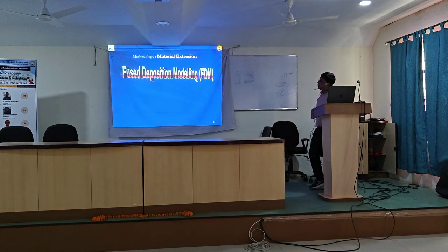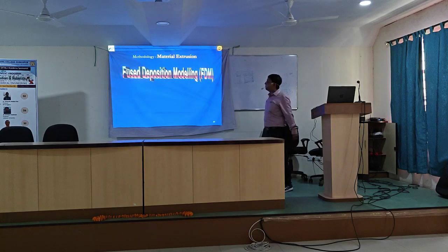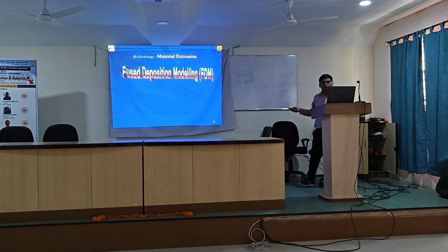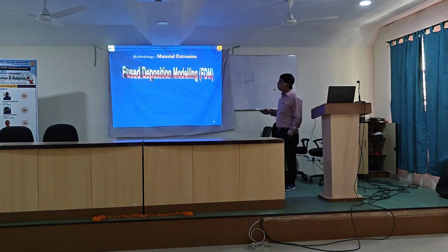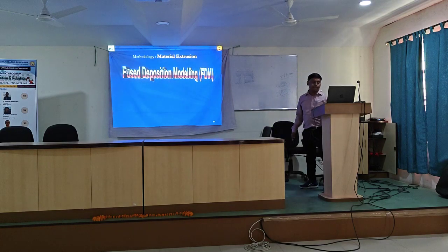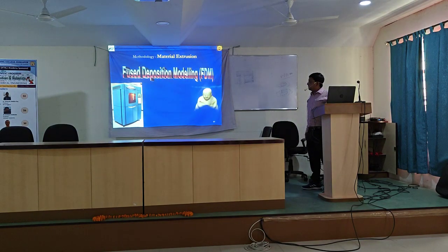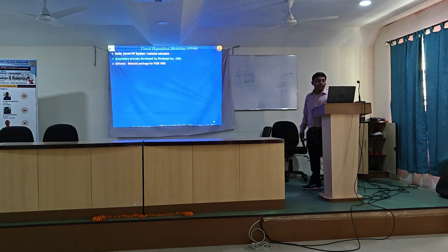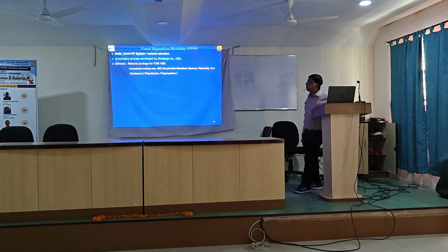So next is a very popular one because of the self-learning mechanism and it is less costly. That is the material extrusion based additive manufacturing process, and the process is the fused deposition modeling or FDM. Now FDM is, I think, available in most engineering colleges. It is your material extrusion process, developed by Stratasys, USA. And the materials used are basically ABS, PLA and different kinds of polyurethane or elastomer.